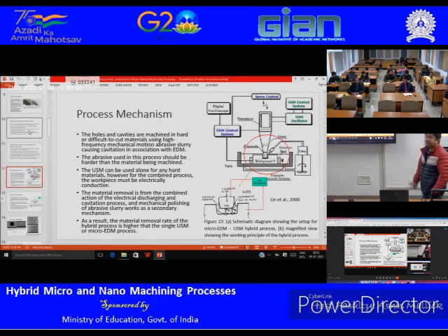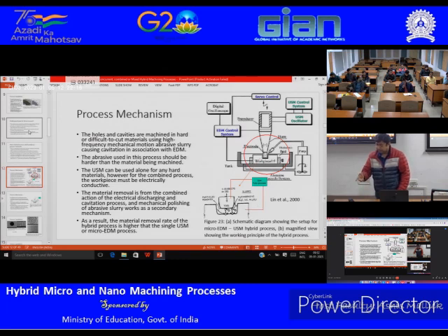How about the flushing mechanism here, sir? Because we are using abrasive particles. The pressure created is how the cavitation happens also, right? The main mechanism of cavitation formation is that there will be some heat generation, and then there will be some pressure differences at the gap and at the outside. That will create some negative pressure, and that will create some bubbles, and those bubbles will collapse. So the negative pressure creation will actually help flush out debris.